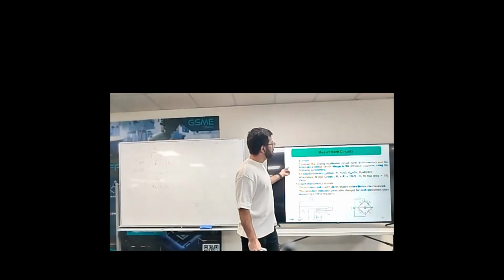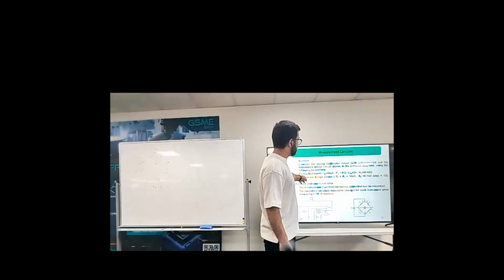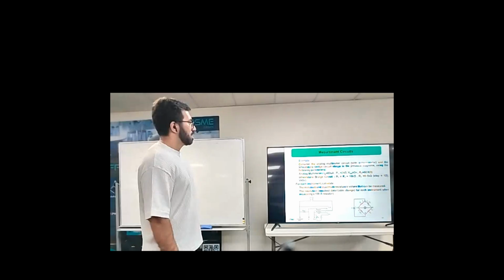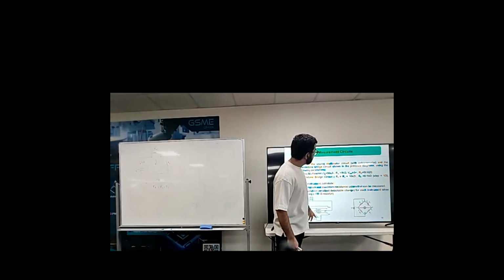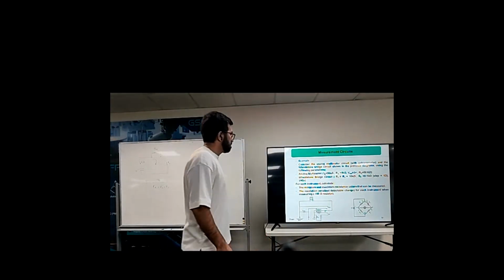We have a Wheatstone bridge here and a multimeter here. We want to measure a resistor. For the analog multimeter, we have these parameters. Its full scale current for the galvanometer is 50 microamp. There is a 3-volt battery, and 50K.